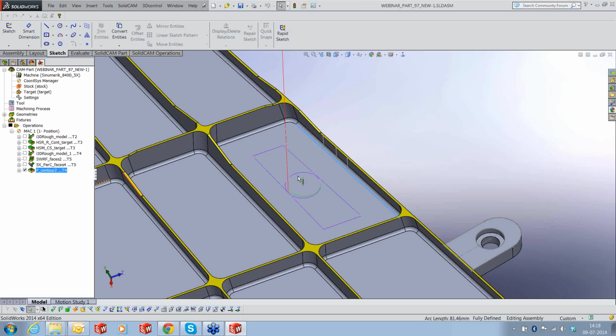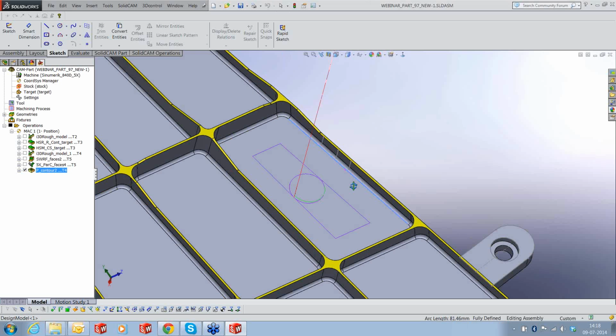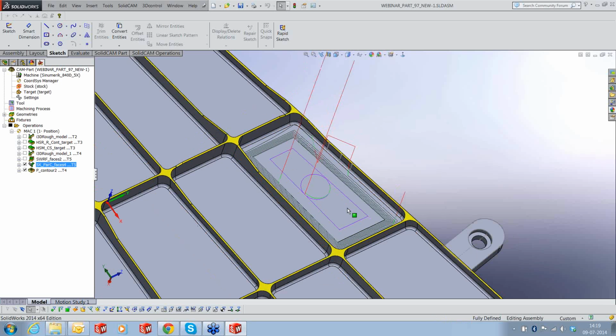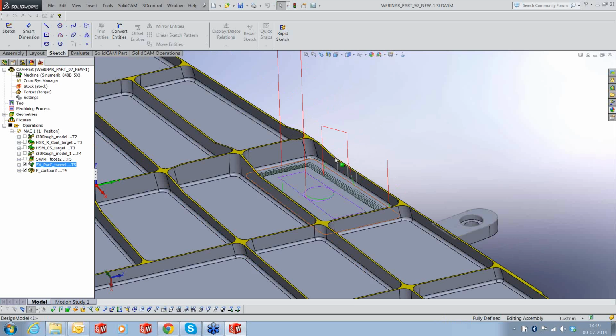So we have just a single toolpath. That should take care of the majority area. So we have this toolpath and this one. Both of them will overlap, so we won't leave any material on the bottom. So what we did now was simple. We created a swarfing, then we created a parallel to curve toolpath with auto tilt to remove that material that comes from the wall onto the bottom area, and then for the remaining one we generated a pocketing function.